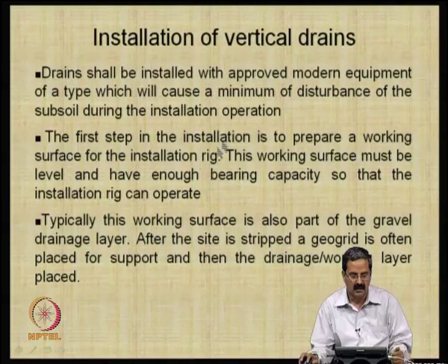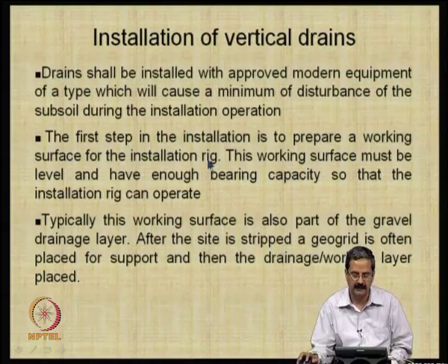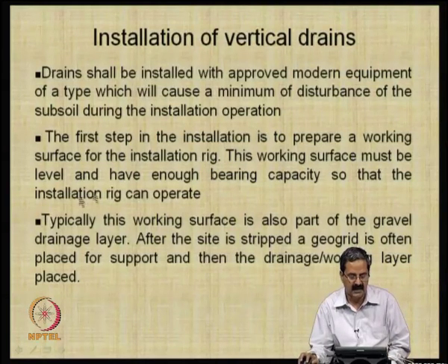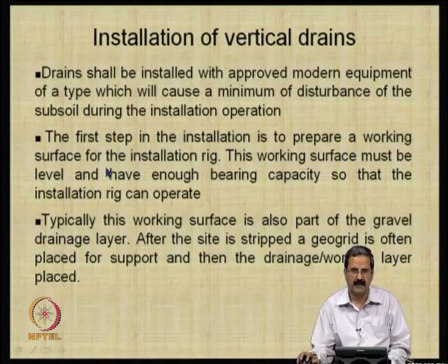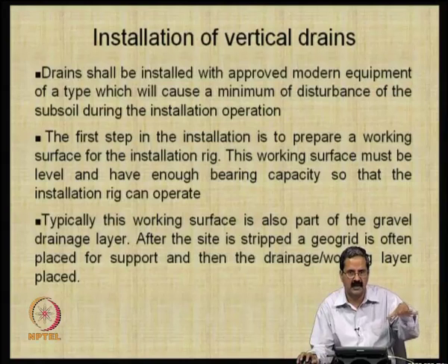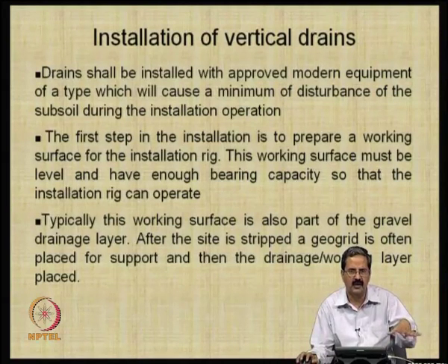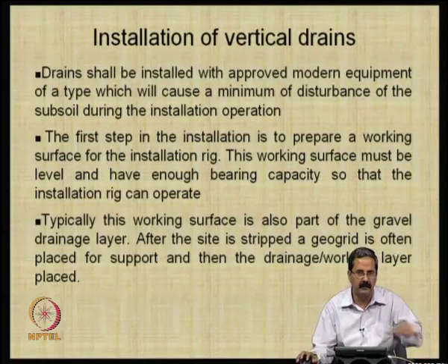issue. And the first step in the installation is to prepare a working surface for the installation rig, like you are bringing a big rig there, and the working surface must be level and have enough bearing capacity so that the installation rig can operate. In fact, you may not believe there are cases where the installation rig can sink in. If the soil is so poor, definitely you can't bring it in. So, you may have to create a temporary platform for it.